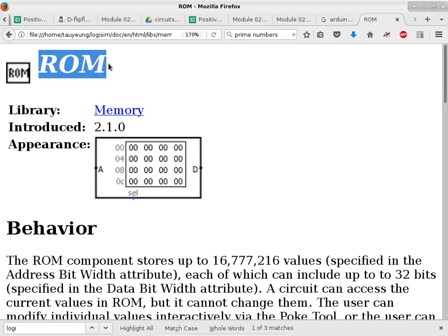Okay, so if you want to manufacture a device that makes use of a ROM, you have to send the specification of the content to the factory or whoever is manufacturing the ROM and say, okay, I need 500,000 of these things. Okay, because it doesn't make sense to say, oh, I just need 5 of those things, because they have to reprogram their machinery in order to program the ROM. And once you program these ROMs at a factory, they cannot be reprogrammed again.